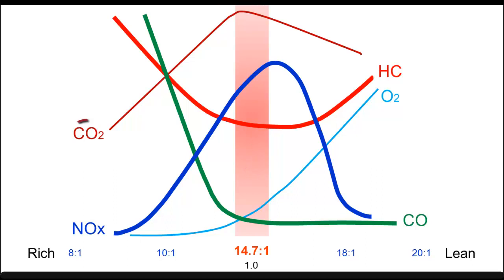Carbon dioxide readings verify stoichiometry at 14.25%. Oxygen at 0.58% supports that. Lambda is at 1.01, indicating near perfect stoichiometry.